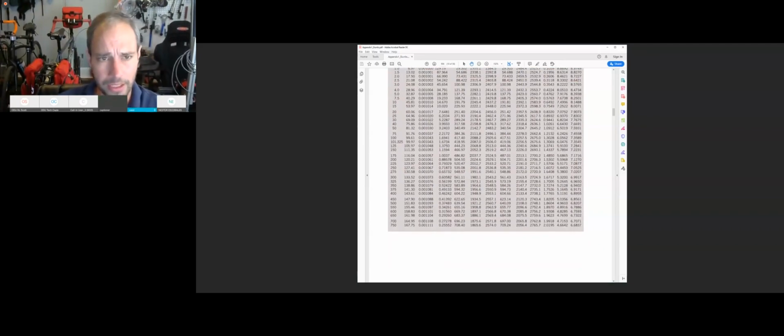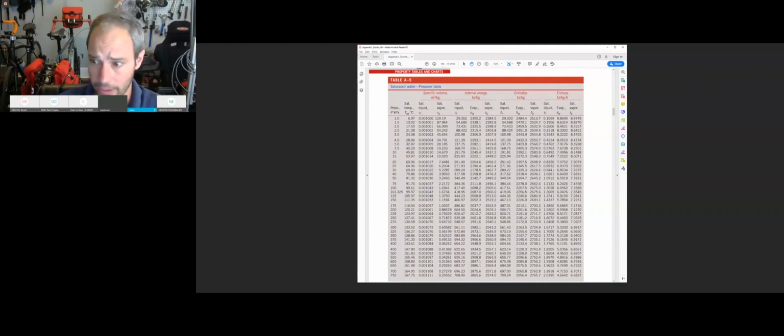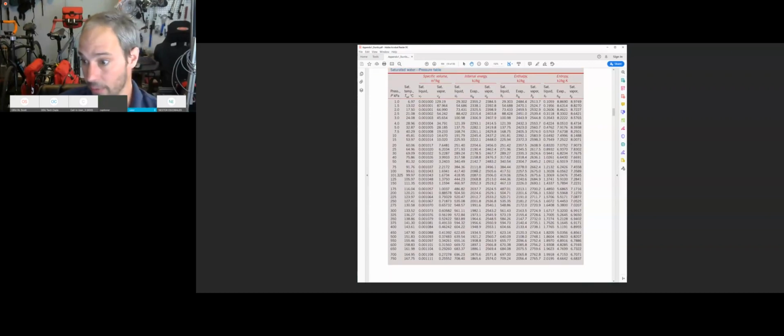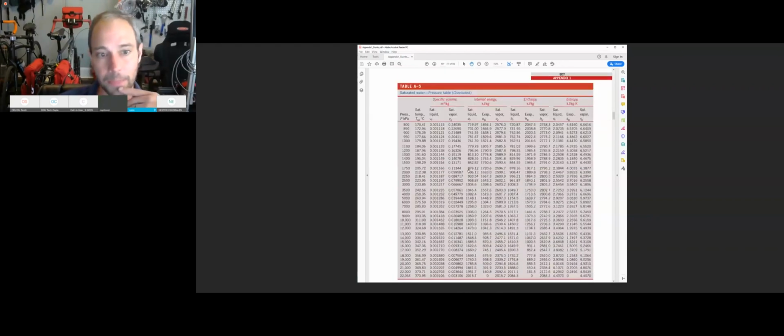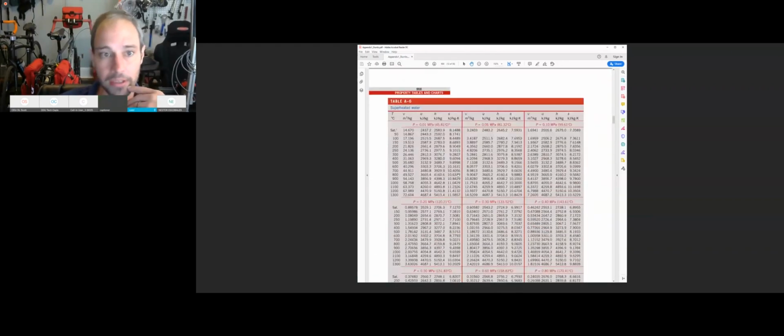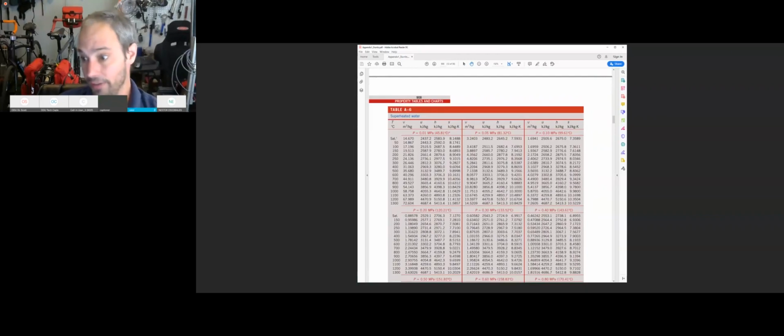So those tables are used whether you're a saturated liquid, saturated vapor, or a combination of the two. We won't get into that either, because you can be 20% liquid, 80% vapor, right? And you use these tables. But if you're superheated and you're no longer a mixture, your temperature is greater than the boiling temperature at your pressure, you come to the superheat tables and you use these superheat pressure blocks. You usually use this for the turbine exit, but in this one, not so much, because our boiler is not a superheater.